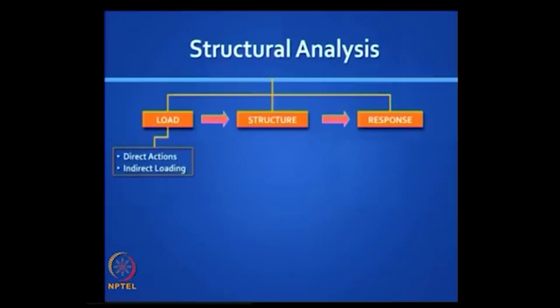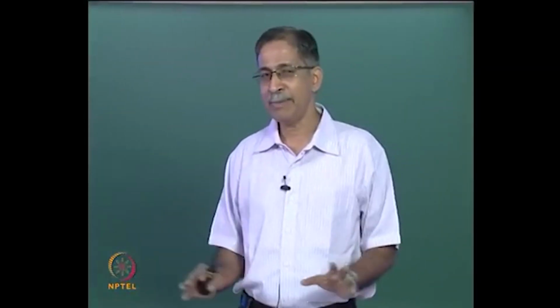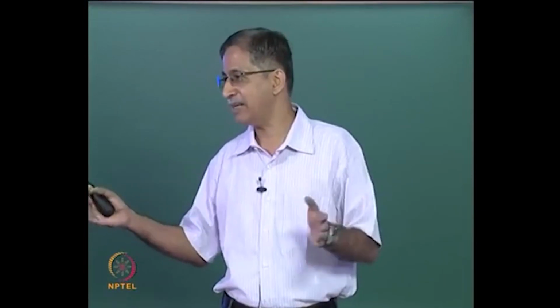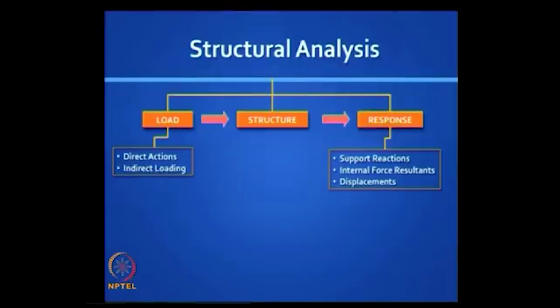So now let us look at the loads. There are 2 types of loads. You can have direct actions and you can have indirect loading. I hope you remember this, and the response is made up of the internal forces, the support reactions and the displacements. Generally we wish to know everything about the force field, but we may not be interested in knowing all the displacements, just a few critical maximum deflections here and there. So that is the difference between the force response and displacement response.